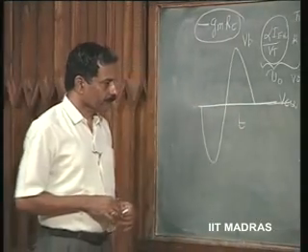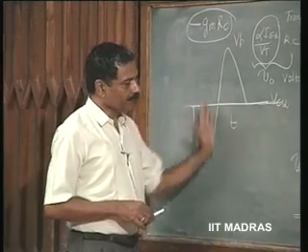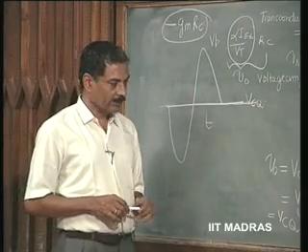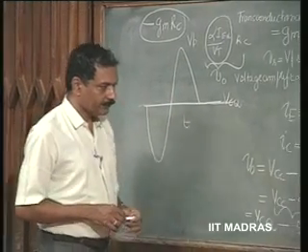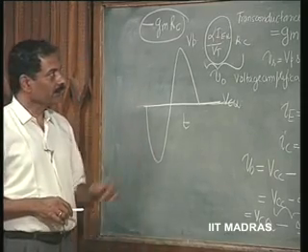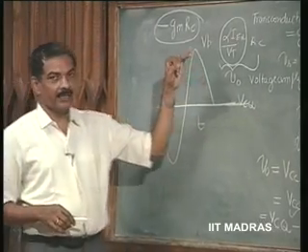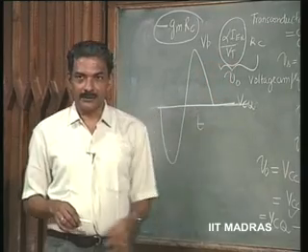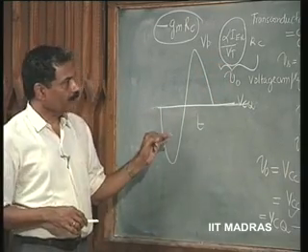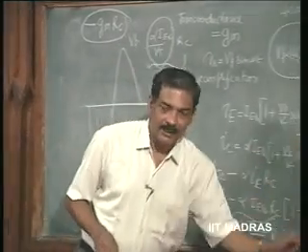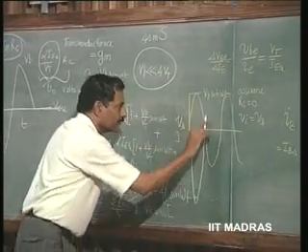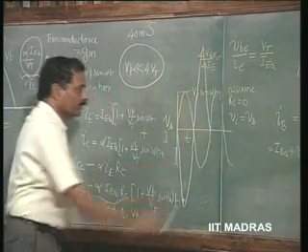Now, this inversion is an important aspect of the amplifier. So, that is why it is an inverting amplifier. That is why the gain is given as minus Gm into Rc, indicating a phase inversion of 180 degrees. A sine wave of this type is going to appear as a sine wave of the other, with amplification.